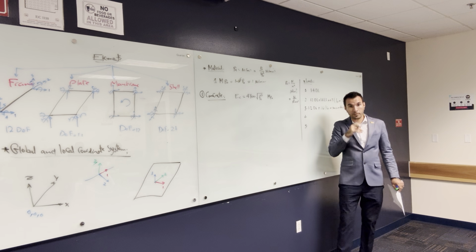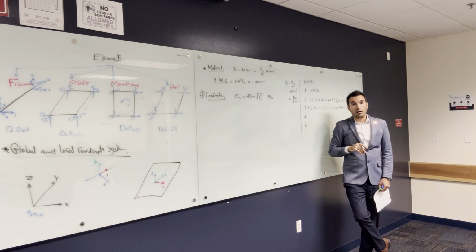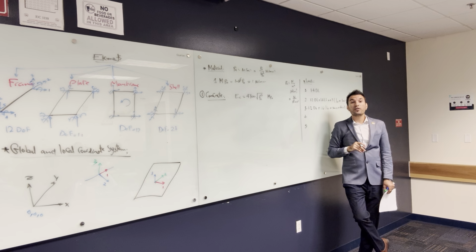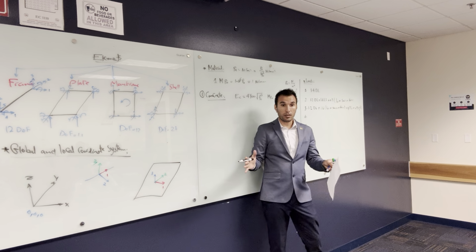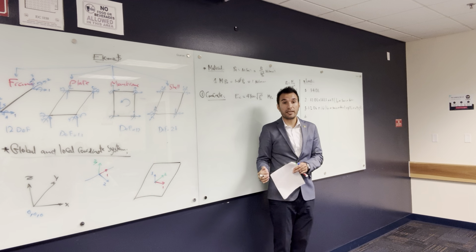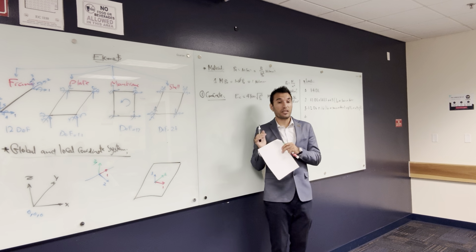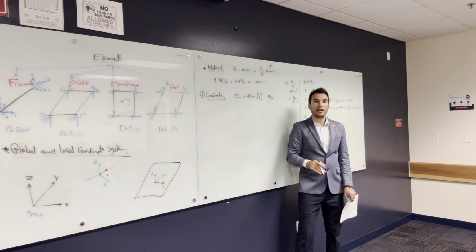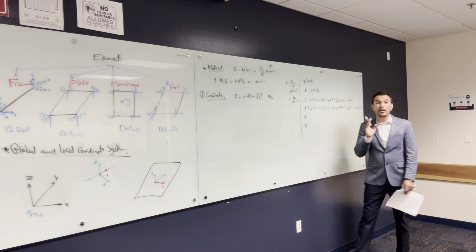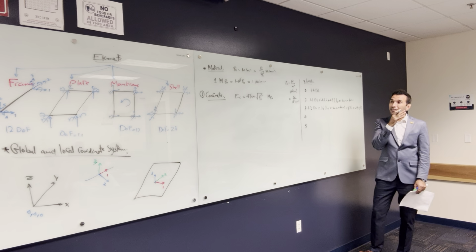Do they drill cores in the slab after it's been poured, or do they grab it when it's still fresh? Before. The thing is, each truck, when it goes to the site, they have to take some cubes from it, and they go test it. If it failed the test, they break it and rebuild. Exactly. From every truck. That's actually the standard test.